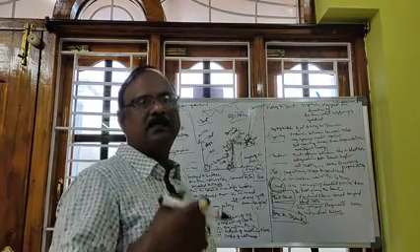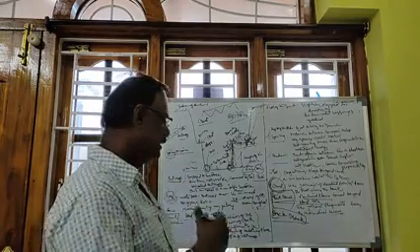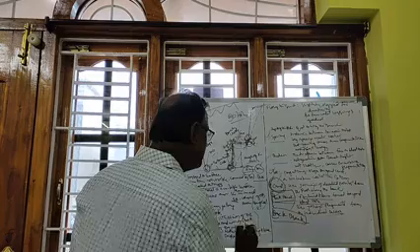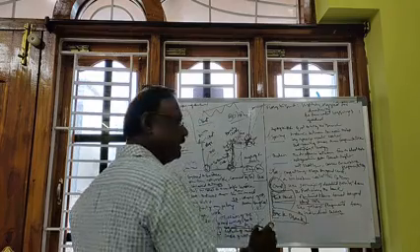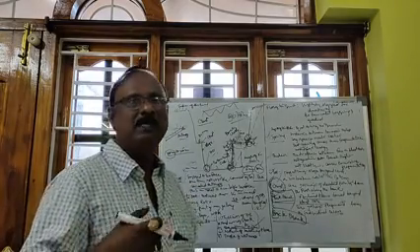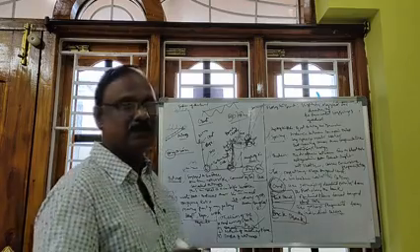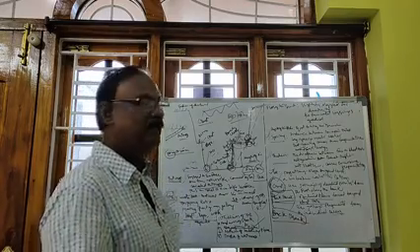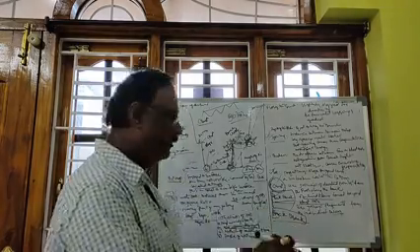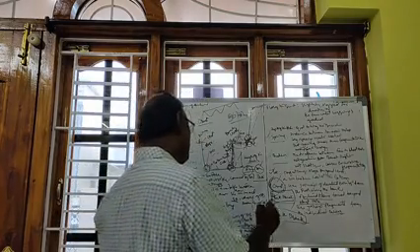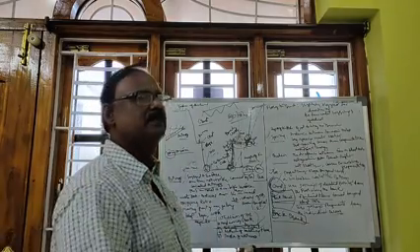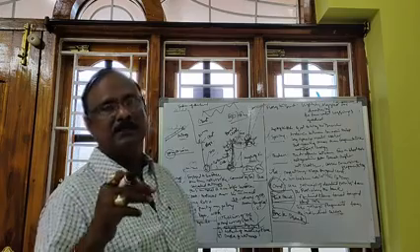Generally the bench height is 5 meters to 30 meters. As we discussed, for a highly mechanized mine, when the equipment size increases, economics allow us to produce even from depth, where even 300 meters of overburden has to be removed and it is economically viable. So technically feasible, economically viable. As mechanization increases, the bench size may automatically be 20 or 30 meters.